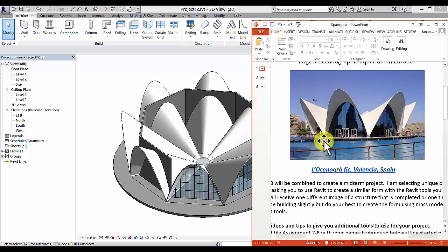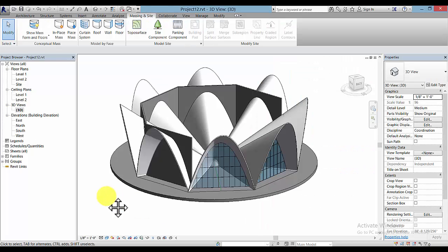If you'd like to add people, or even create another circle that would define the water. Okay, we could take it to another step and create topography and change that topography to water. In the assets, there is a material called water. This works for showing the form. If you do create topography, you want to go lower than the floor level when you're creating your elevation.